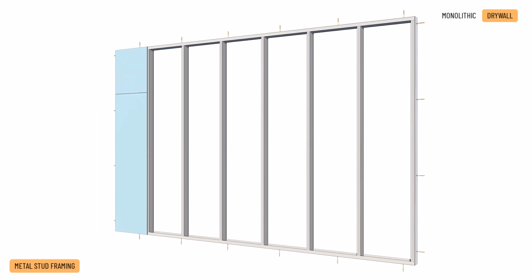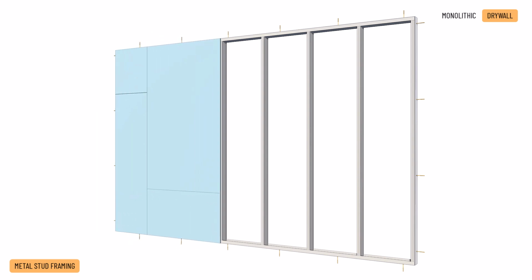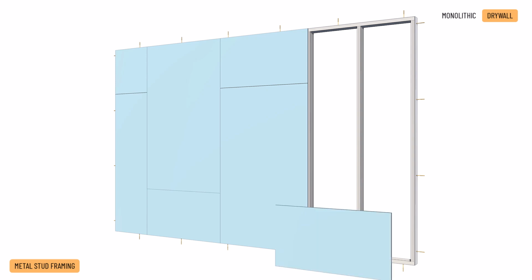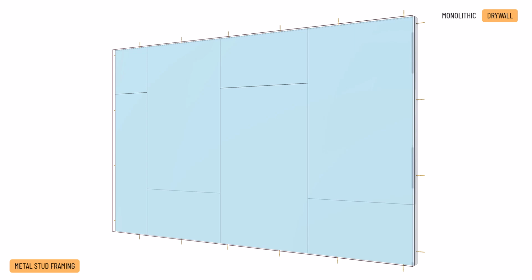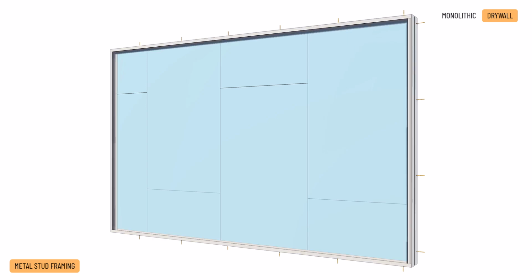6. Next, we attach a single layer of gypsum board to the profiles using self-adhesive strips. The boards are kept 6 to 8 mm from the bottom concrete. The gap is filled with silicone. 7. By repeating points 4 to 6, we construct the second stud framing, closely adjacent to the already installed single layer of gypsum board.